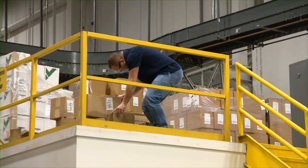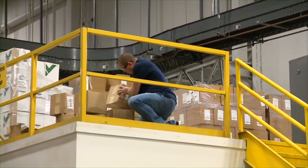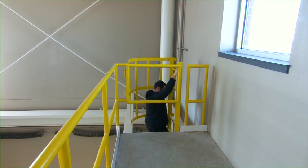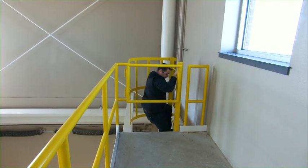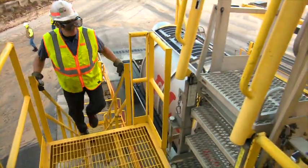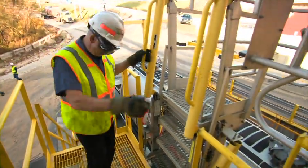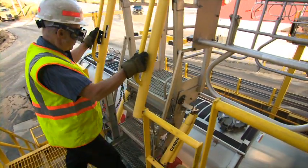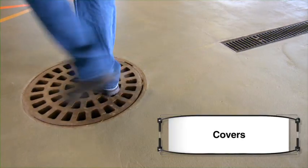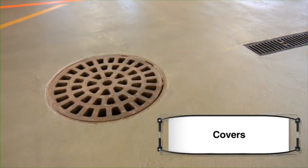The mid rail must be midway between the top rail and the surface below. These systems can be used to protect you from falls, from unprotected sides and edges, through holes including skylights, from ramps, runways, or other walkways, and into or onto dangerous equipment. Covers are secured, removable caps that are strong enough to prevent workers from falling into or through a hole.